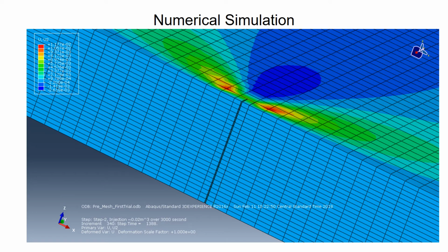In order to understand how to implement XFEM-based CZM in Abaqus, we ran a simplified model with an initial crack length that was unrealistically large, but converged very easily. After successfully simulating XFEM in this model, we made changes to make it more realistic. Our project involves the construction of a 15-cluster model in Abaqus using XFEM-based CZM to simulate fracture propagation in a three-dimensional setting.